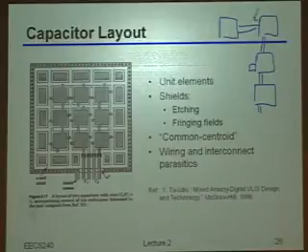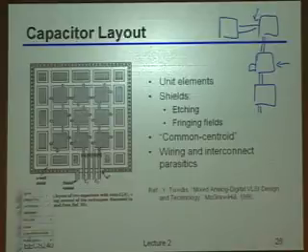Because here, this capacitor has something going to the left, this capacitor has something going up, and remember I said it has to be exactly the same? This is indeed the level of paranoia you have to have when I say exactly. Because left versus vertical is not necessarily the same. In fact, in some modern technologies, even the rules for doing layouts on vertical versus horizontal lines could be different. So what was done here was trying to make sure that, even when you think about how you connected things together, the parasitic capacitance or the total capacitance would match between those things.